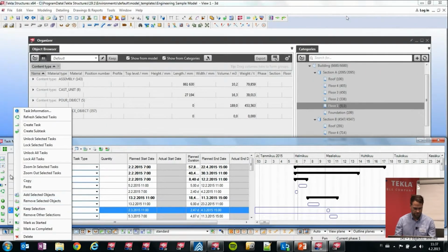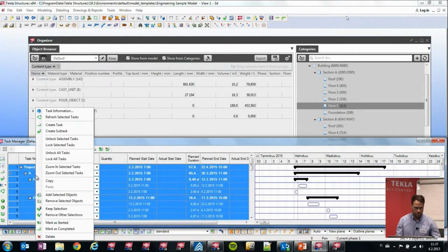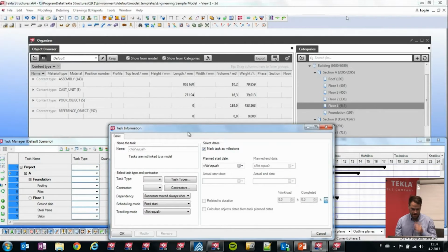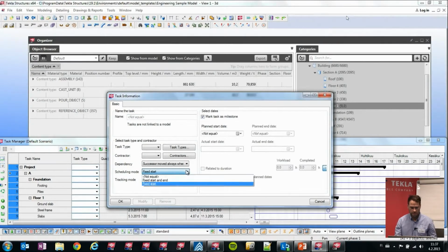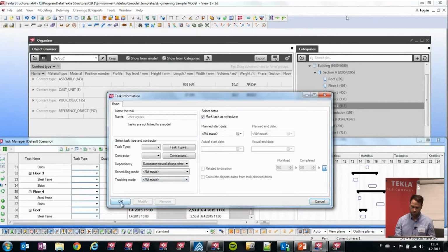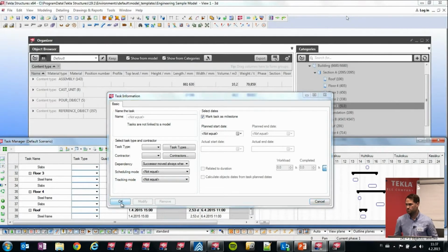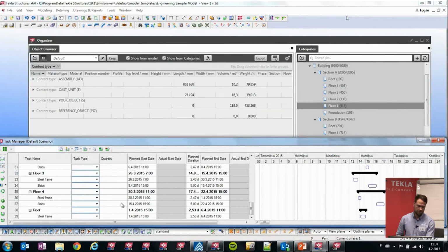And then say just this. I need one thing first, yeah, we need to lock the schedule that I imported from Tekla, because I don't want to calculate the duration in Tekla. I'll keep the duration that I calculated and planned in VICO. So it's like a baseline.